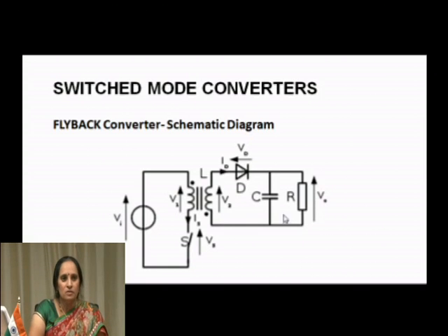Okay. So, now the working of this circuit should be done for two modes. One is when the switch is closed, what happens to the current flow and what happens to the voltage, and then after some time when the switch is open. So, please see, in switching mode converters, I am talking about how long the switch will be on, how long the switch will be off. Pulse width modulation is what I am dealing with. It may be BJT, it may be MOSFET, it may be IGBT as switches. Okay. So, let us see its working in those two modes.